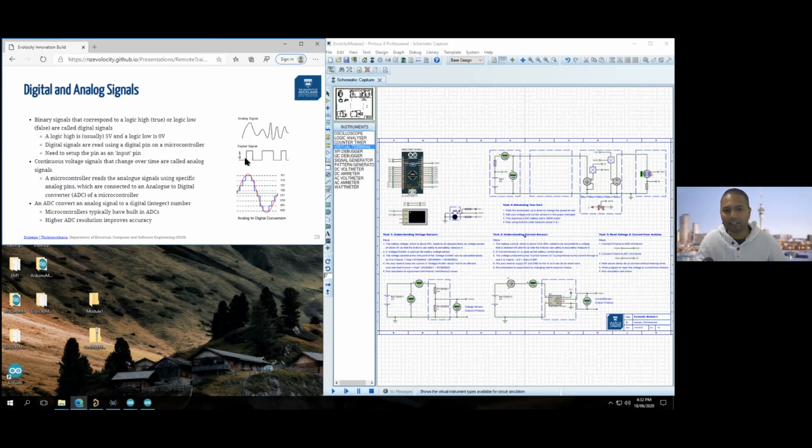If you compare that with a digital signal, the digital signal only exists in two different states. It's either a 0 or a low, or a high or a 1. And as time goes on, the state, whether it's a high or a low or a 0 or a 1, would change, indicating your digital data. Now, we had to take this analog signal and convert it into digital in order for us to be able to measure the voltage and current using the microcontroller or the Arduino, and then process it using algorithms, if-else statements, and mathematics, in order to work out the power, the capacity, all these sorts of things.